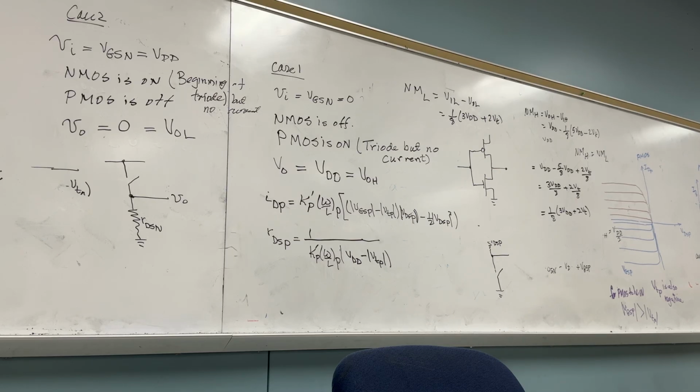When you have capacitors in parallel, will the overall capacitance be higher or lower? Higher. Because with capacitors in parallel, when you find the equivalent, you treat them as what? As resistors in series. Do you remember? Yes. It becomes higher and higher. So the more gates you drive, the input capacitors of each of these gates will be in parallel, resulting in what? Higher capacitance.